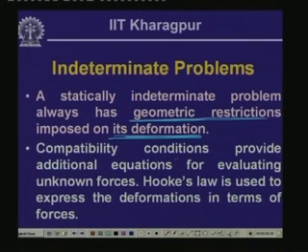So, compatibility conditions provide additional equations for evaluating unknown forces, and thereafter we can adopt Hooke's law to express the deformation in terms of forces, because we first write down the compatibility criteria based on the deformation, and then we adopt Hooke's law to relate the deformation to the forces, and finally we get equations from this compatibility criteria which help us to solve the unknown reactive forces.